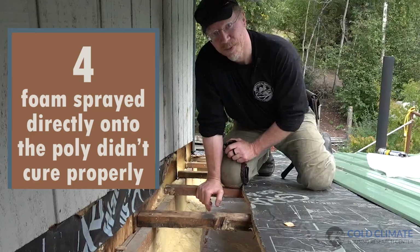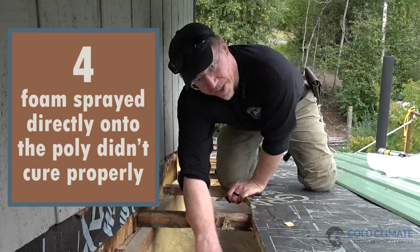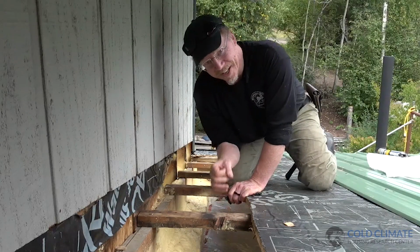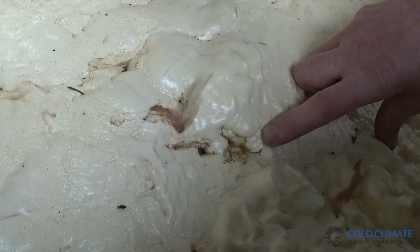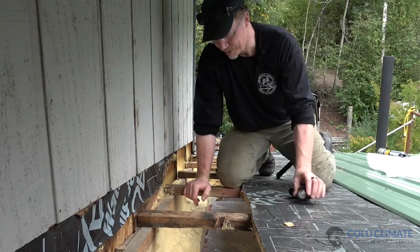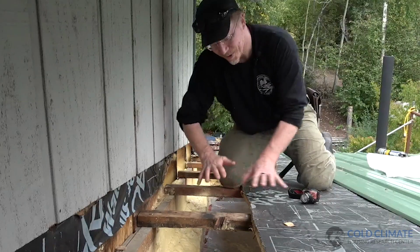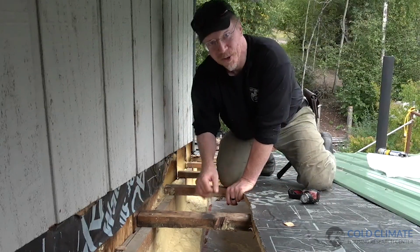And that's our fourth problem. Because this foam, we theorized, didn't cure properly being applied over poly, it had a series of small holes. Actually, some of them were about the size of my pinky. And that's where the smoke came out of. And I think we probably had 8 areas like that that we now have to seal, because remember, the foam isn't bonded to the poly. Indoor air is migrating between the foam and the poly until it finds a hole.